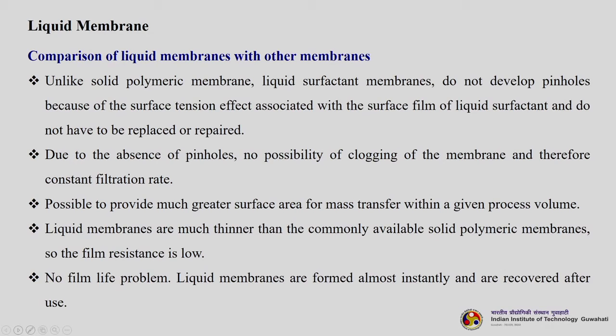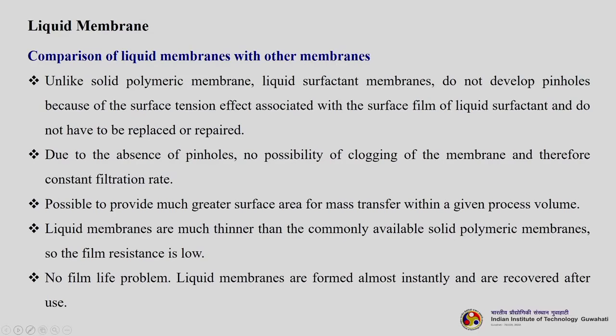Unlike solid polymeric membranes, liquid surfactant membranes do not develop pinholes because of the surface tension effect associated with the surface film of liquid surfactant, and do not have to be replaced or repaired. So, this is one of the biggest advantages. Then, due to the absence of pinholes, there is no possibility of clogging of the membrane and therefore a constant filtration rate. So, there is no question of any concentration polarization happening as in the case of solid membranes.